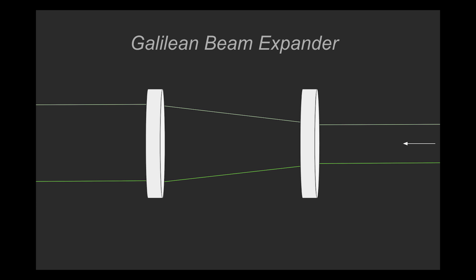An alternative approach to this technique includes using a Galilei beam magnification system, which utilizes a dispersing and collecting lens, rather than two focusing lenses, to prevent overheating within the system at the focal point of the first focusing lens. This is particularly helpful if you are limited in space.